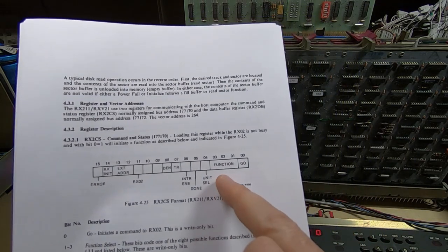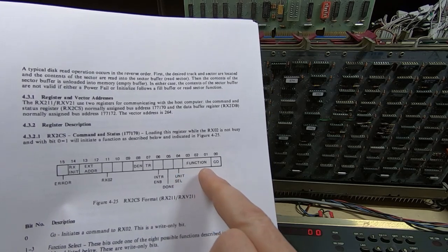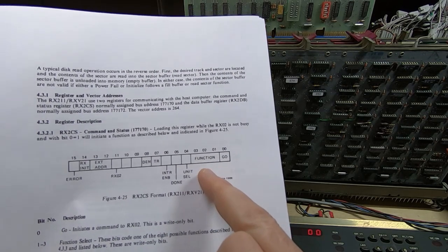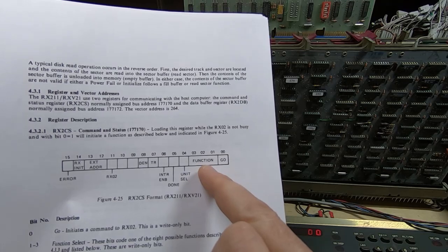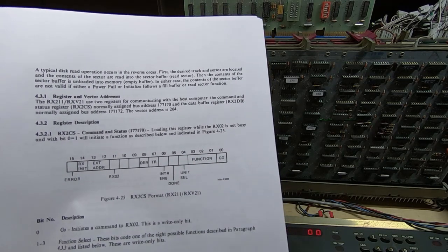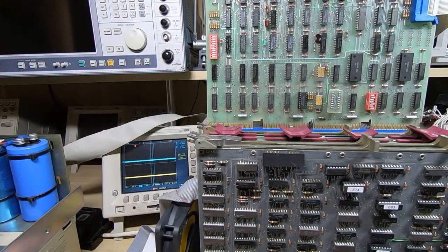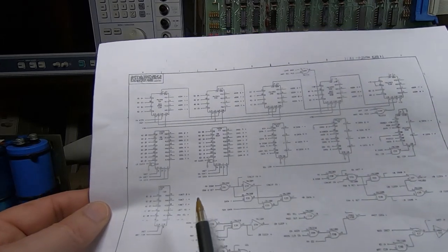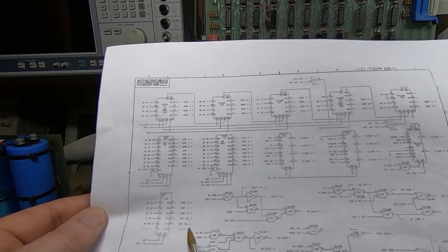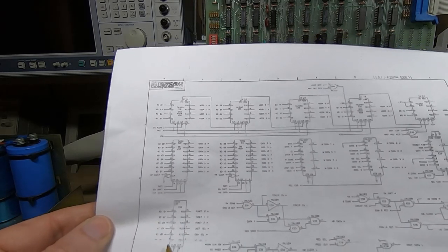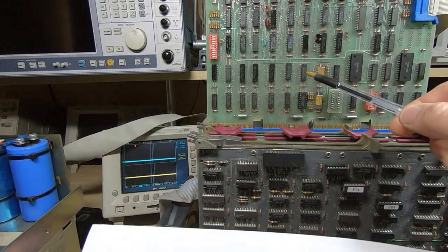What I'm going to do now is make sure that the RX211 can successfully accept the function values we're sending to it. So I'll move the camera and we'll send various functions to the board and make sure that the latch that accepts this is actually working. I won't go through the entire schematic, at least not in this video. If you're interested, let me know and I'll go through the RX211 card in more detail once it's up and running. But we're looking initially at this latch here, and it's E37, so that's this device.